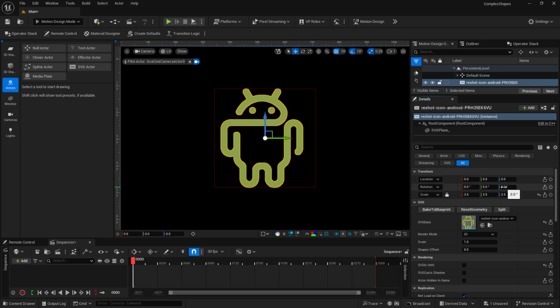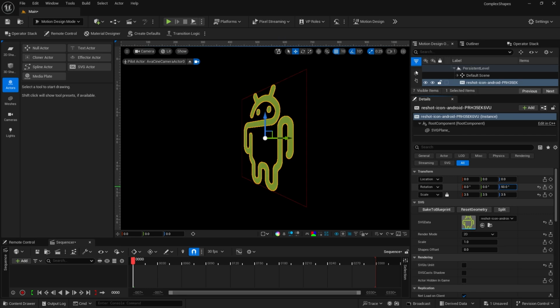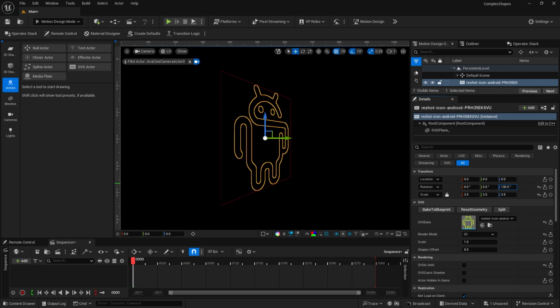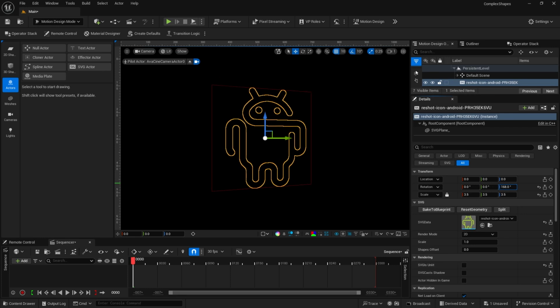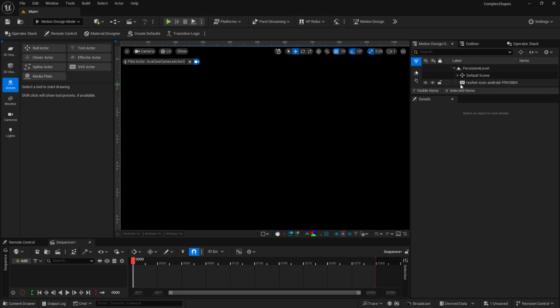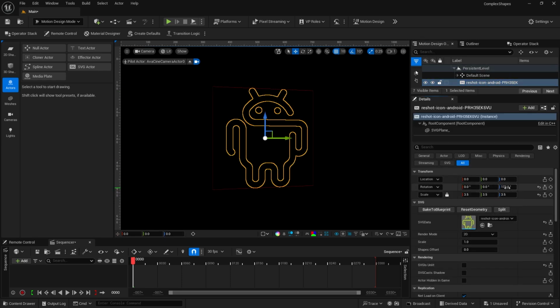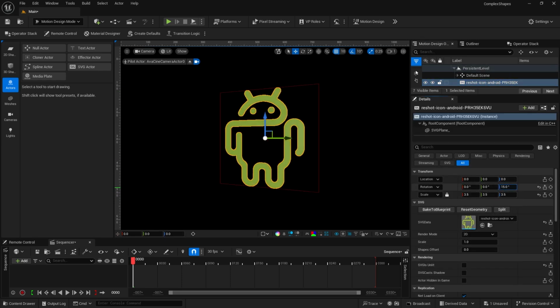And now the material that has been imported with it will respond to the lighting in the scene. I am going to go ahead and rotate this because I want to show you on the back side of this, this is not a two-sided material. So if you go to the opposite side of this, the back side of it, you'll see that this is no longer showing up. That is an issue, especially if you're working with 2D and 3D space. There's really not an option to change the material or the color of this object in 2D mode.